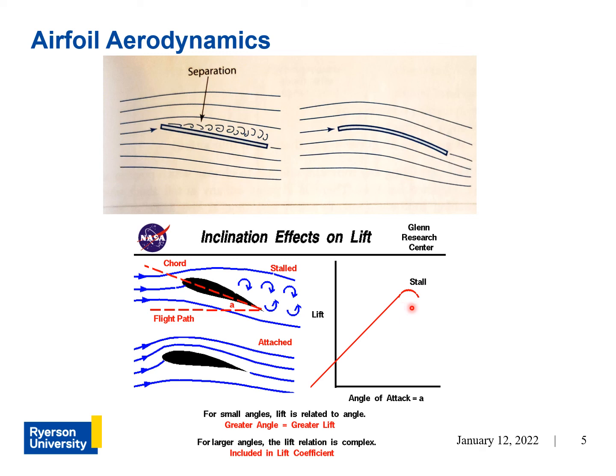And when stall occurs, there is a loss of lift, as you can see here, as well as a large increase in drag. And that's because here, as your flow separates, the region of air here underneath the wing or airfoil is of a much higher pressure, and over here there's going to be a lower pressure, so there's going to be a net pressure drag. That's what they refer to it as, that is caused by the flow separation.